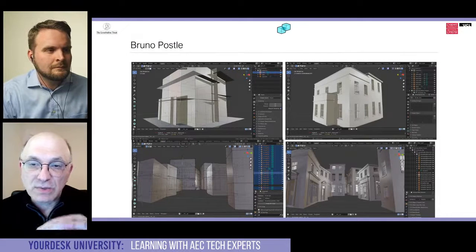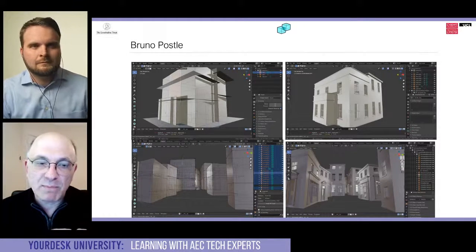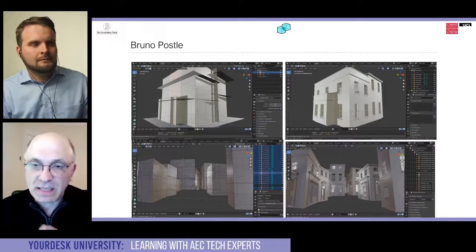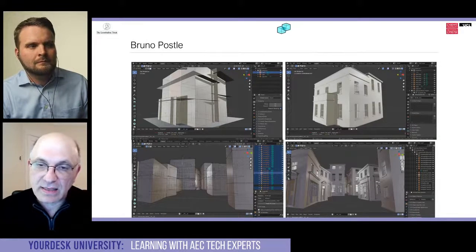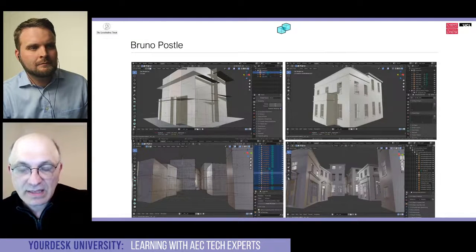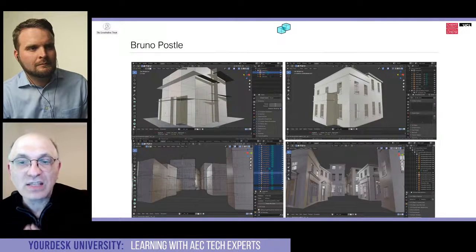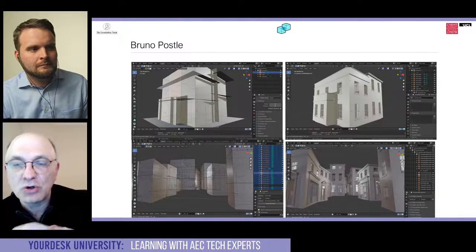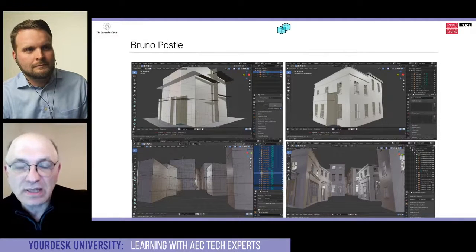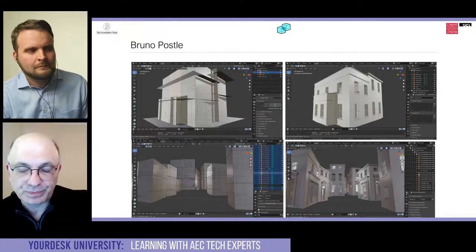So it is really powerful to be able to think of a building as this kind of volume that gets subdivided by faces, and then you get the result. But also, when you get that result, you can ask questions of these cells. When you have a cell, it's not just a cube that happens to be sitting next to another cube. It knows the adjacency information.